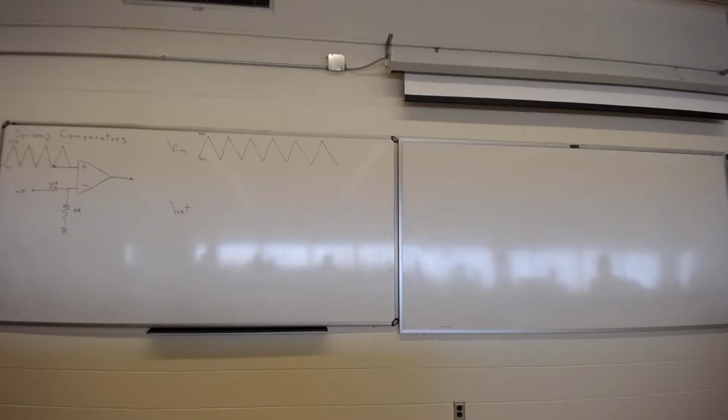This is a very simple one that we can build with an op amp. Just to let you know, when you are using comparators, there are packages that are specifically made just for doing comparisons. So you can buy an op amp comparator that's its only job. That's what it's designed for. It doesn't mean you can't use an op amp to do it, but there are slicker packages around that will permit you to have better results. But this will work.